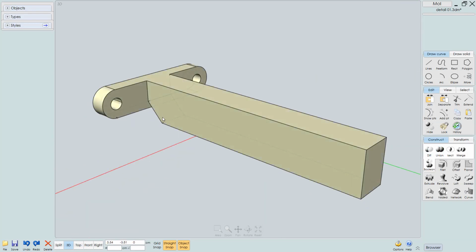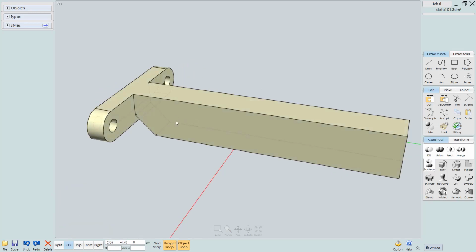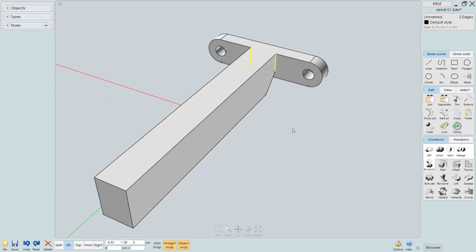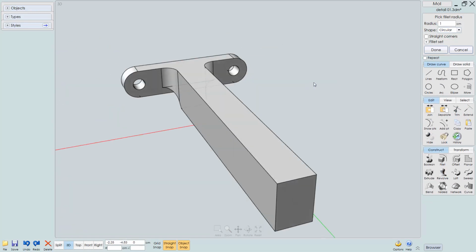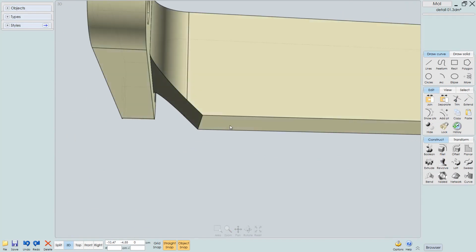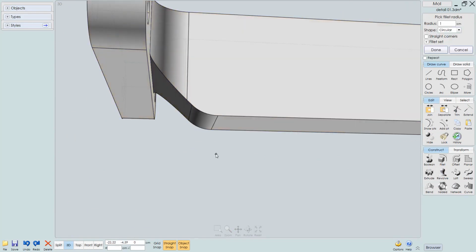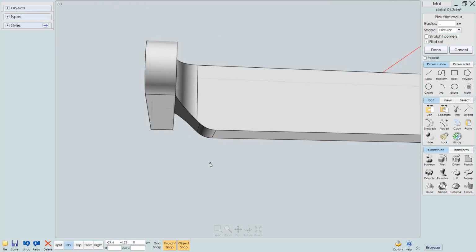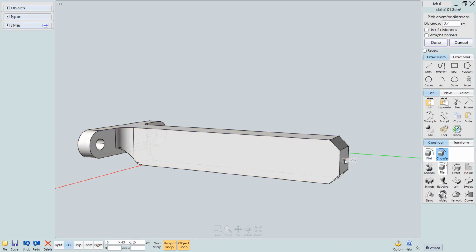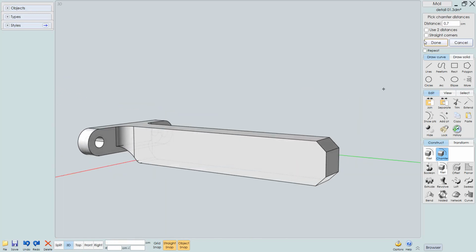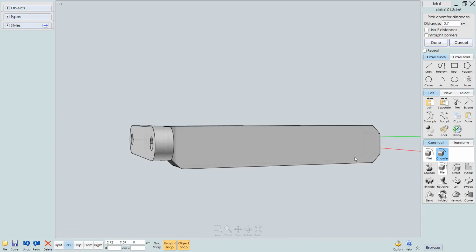And I want to make this object look a little more interesting. So I'm going to change some of the corners here and add some fillets right away. Let's select these ones and fillet them. Let's try an offset of 1. And I think that's looking good. I'm going to add another fillet down here. Let's make this 0.5. And let's add maybe a chamfer to these corners here at the back. 0.7 is actually looking good, so I'm going to keep that.